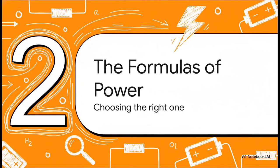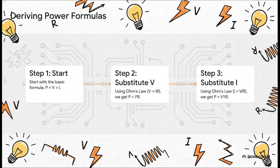So we have our main formula, P equals V into I. This is our starting point. But what happens in a numerical problem where you are given the current and resistance, but not the voltage? Or maybe you have the voltage and resistance, but not the current? Well, this is where our old friend Ohm's law comes to help us. We can use it to create 2 more very useful forms of the power formula. Let's see how this works.